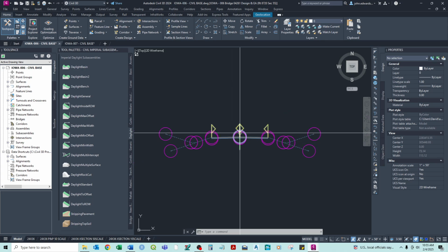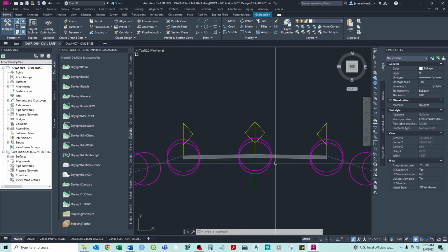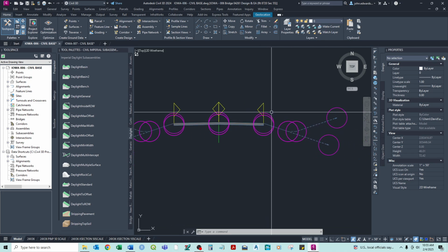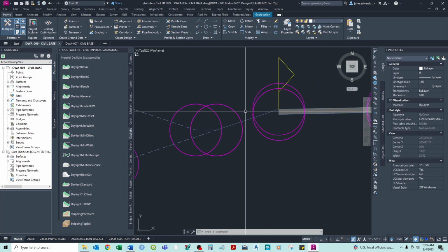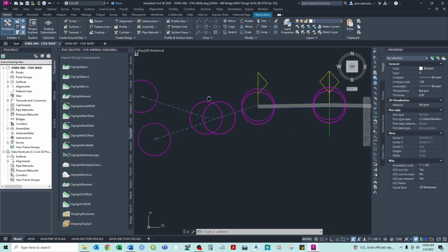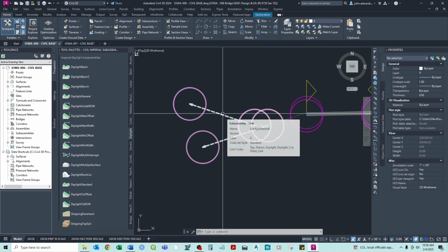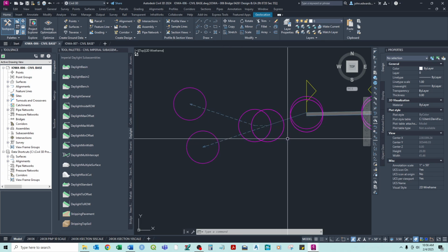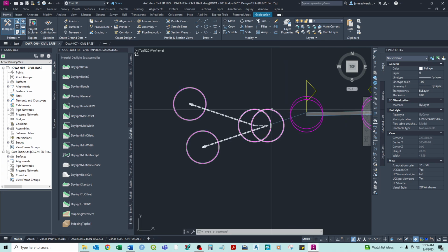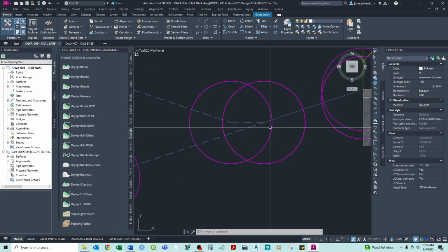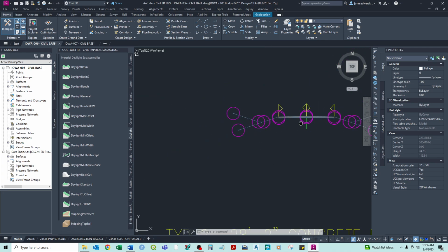Okay, good. So the difference when you're doing subassemblies and you're actually selecting marker points, you're not necessarily selecting endpoints or general snapping points. You're basing it off of these markers, because for each subassembly feature, these markers determine the features of that subassembly and how it functions and works. And so that's why you're tying in. It's not an endpoint. These are flexible objects, and so they need to be tied in directly to each other.